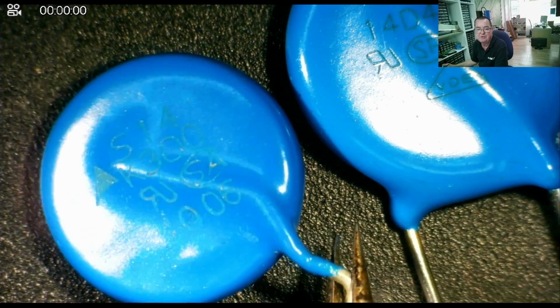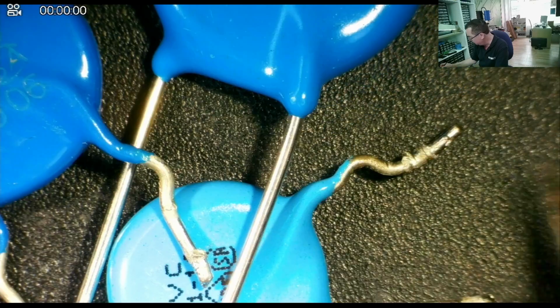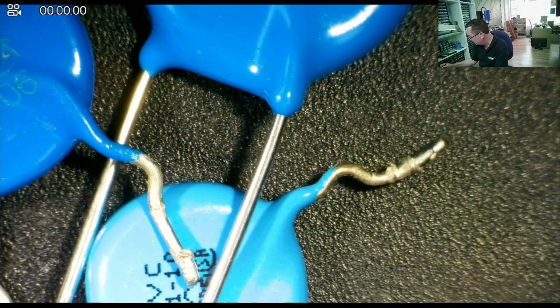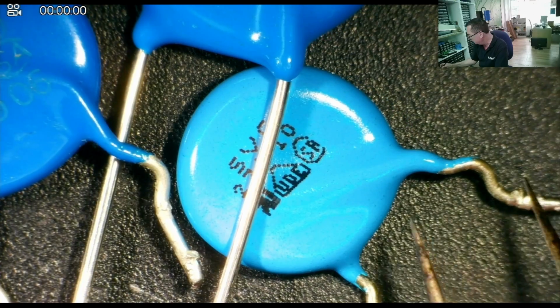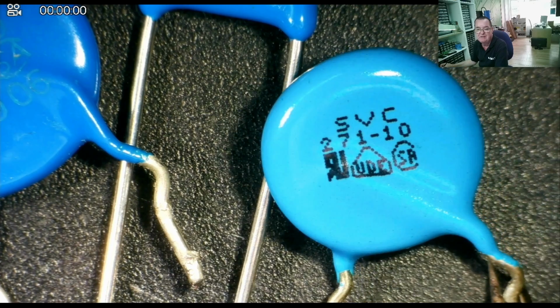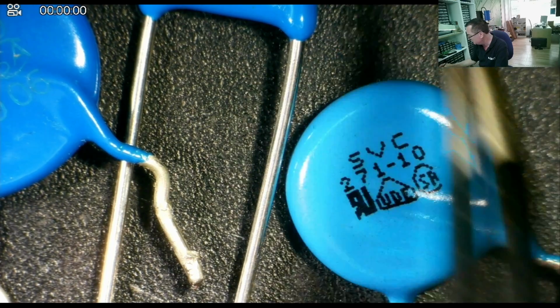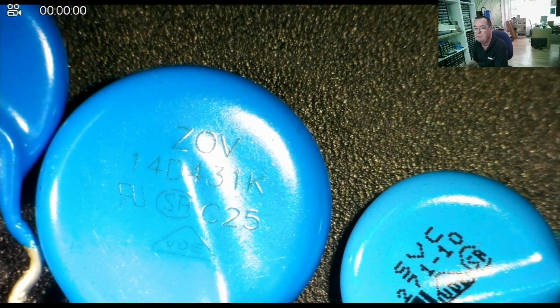These capacitors are not capacitors. Okay, they look just like those blue things we were looking at, those high voltage capacitors, but they're not. These are voltage dependent resistors, or MOVs. They're normally connected on the input to mains equipment and elsewhere, effectively to prevent voltage surges. So those are not capacitors, okay? Don't let that confuse you when you see them.